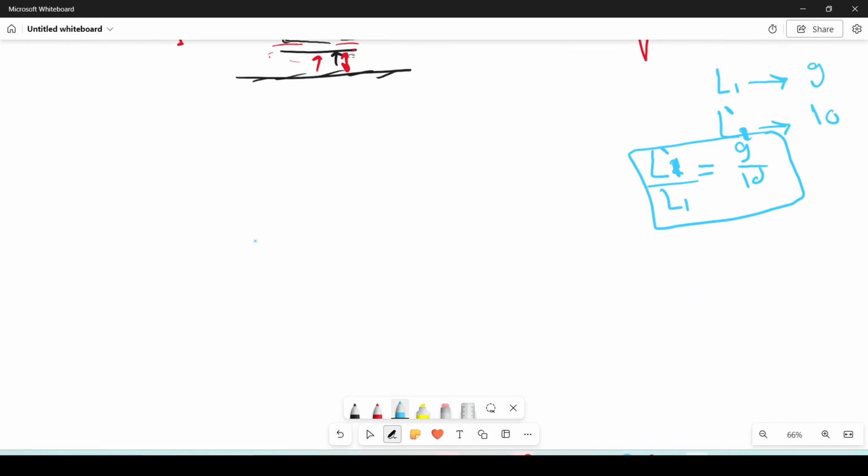So we feed by coaxial, this thing, and this is the inner conductor, this is the outer one, and we have epsilon like this. Any transmission line is like this. Everything is connected to the capacitance. If you know the capacitance, then you know Z0. So it is basically determined more by the ratios of the diameter.